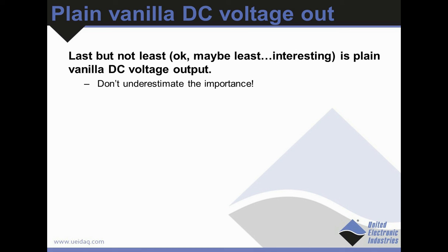But don't underestimate the importance of it, because I think we find that, especially in the simulator, not quite as much as in the SILs, probably half the signals that we need to simulate are just voltage signals, plus or minus 10 volts, or sometimes in aircraft it can be plus or minus 28, or automotive or truck and that kind of thing could be plus or minus 12 or 24. But there's almost always a significant requirement for voltage output.